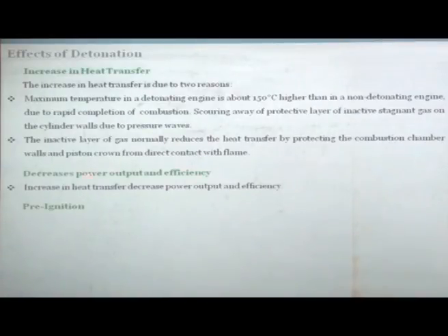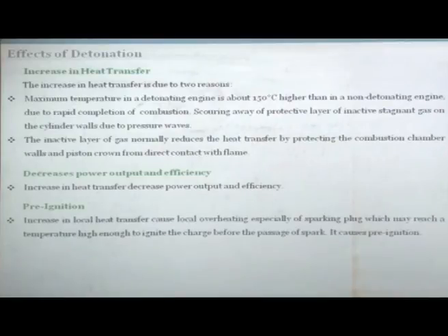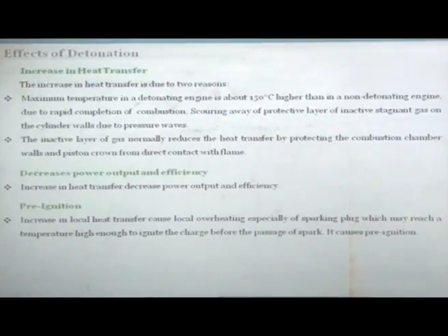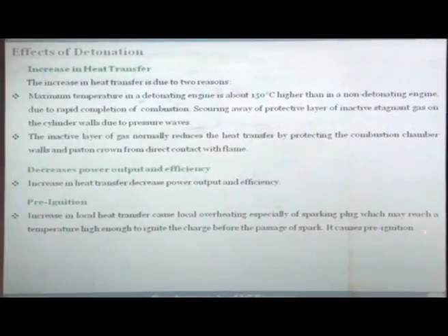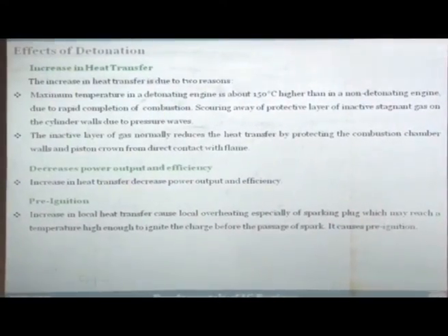Okay, this will lead to high heat transfer losses, and therefore it will lead to reduction in power output and reduction in engine efficiency. We have seen that if there are places where the engine runs hot or if there are carbon deposits, it will lead to problems such as pre-ignition. Okay. So increase in local heat transfer causes overheating, especially of the spark plug, which may reach temperature high enough to ignite the charge before the passage of the spark, and it will definitely cause pre-ignition.